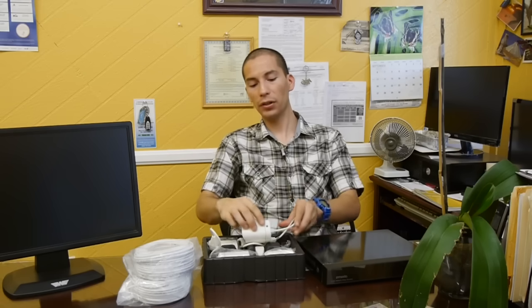Now you need to figure out where you're going to place your DVR and your cameras. You need to make the best use of your cameras, so placement is very important. It's always a good idea to place them near entrances and exits, high traffic areas, and locations where important valuables are located. If you're going to be placing these outside, you want them to cover the largest areas possible, and also place them high enough so they can't be reached and tampered with. As for your DVR, you don't want to place this in your main room or in an area with high traffic. You really want to keep this out of sight.